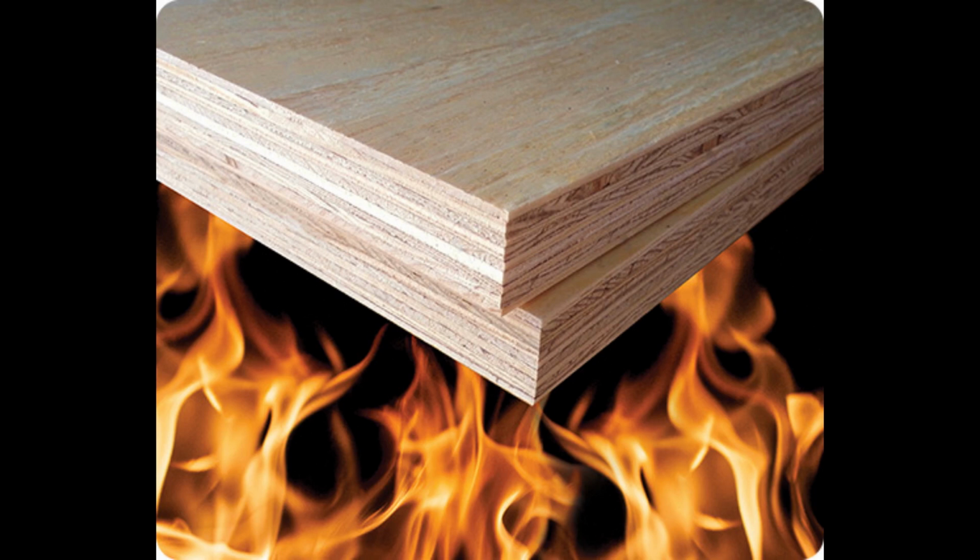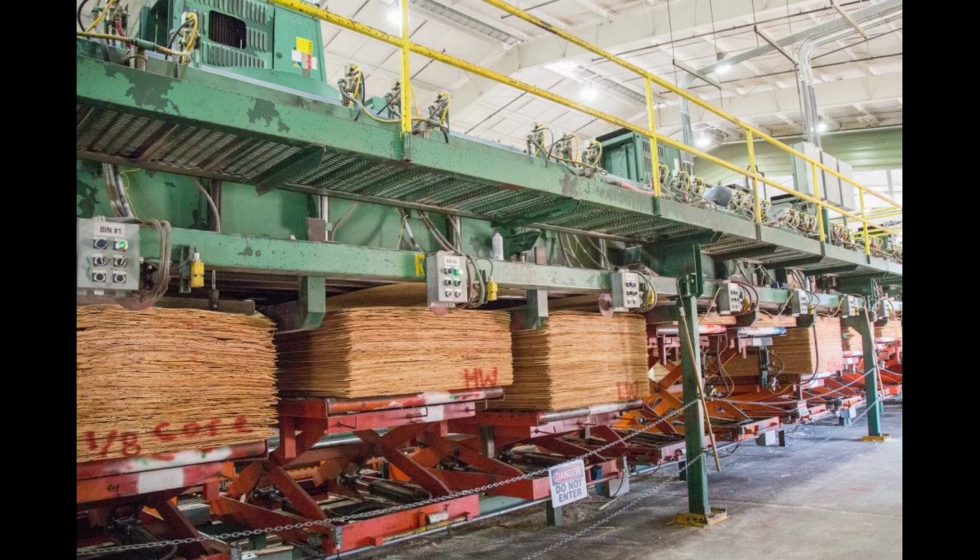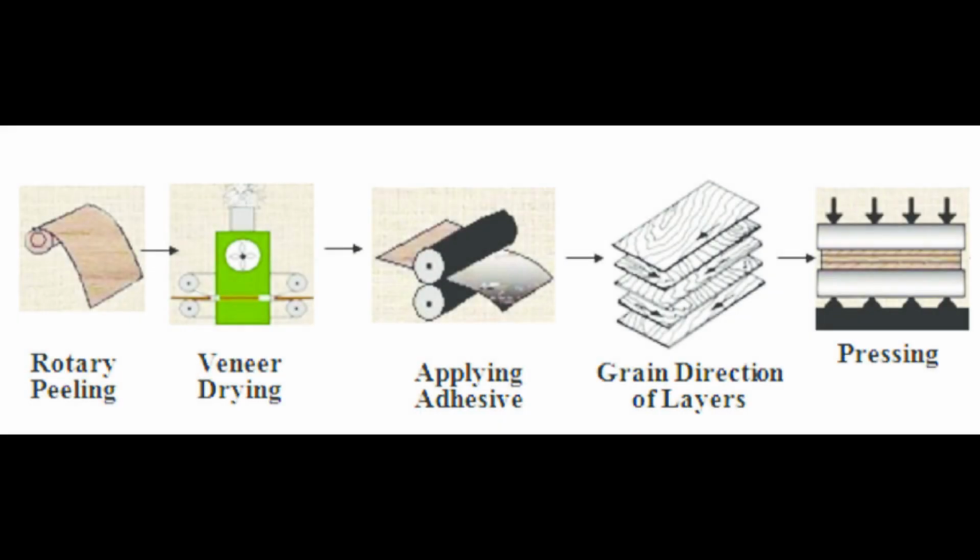So now let's see how the logs for plywood construction in a plywood factory are made. Plywood production requires a good log called a peeler, which is generally straighter and larger in diameter than one required for processing into dimensioned lumber by a sawmill. The log is laid horizontally and rotated about its long axis, while a long blade is pressed into it, causing a thin layer of wood to peel off, much as the continuous sheet of paper from a roll.